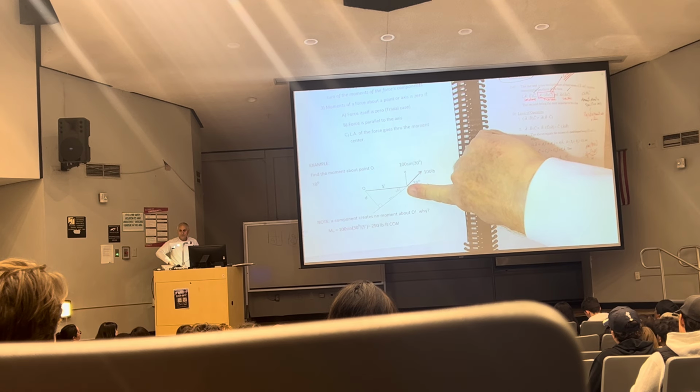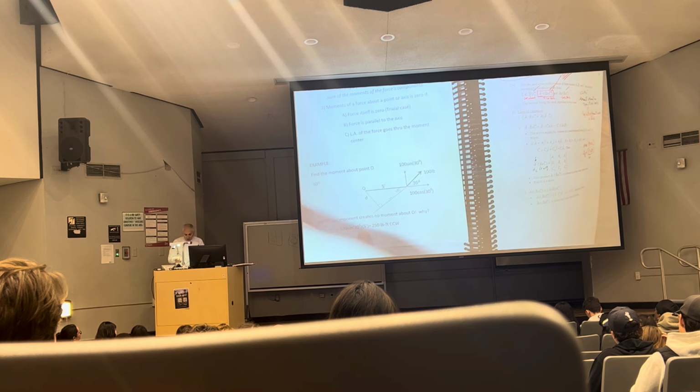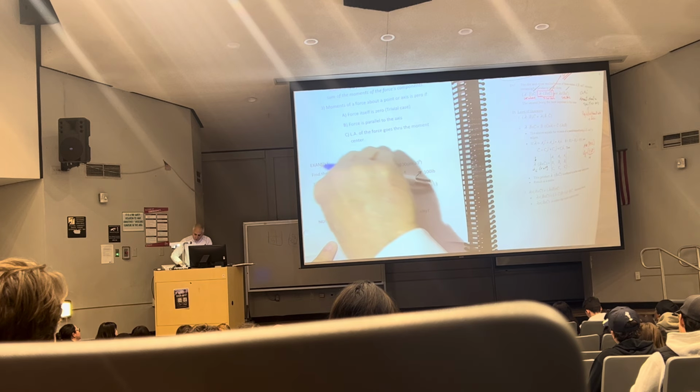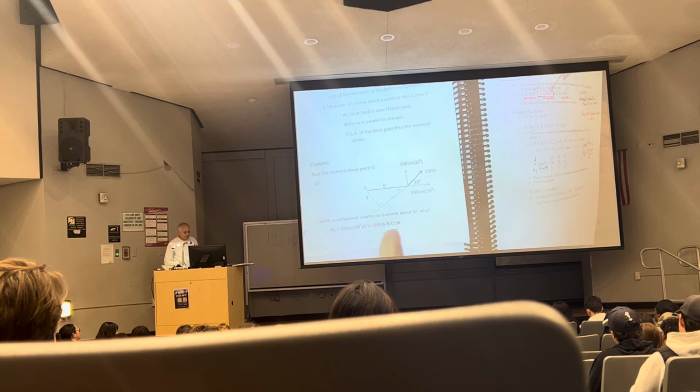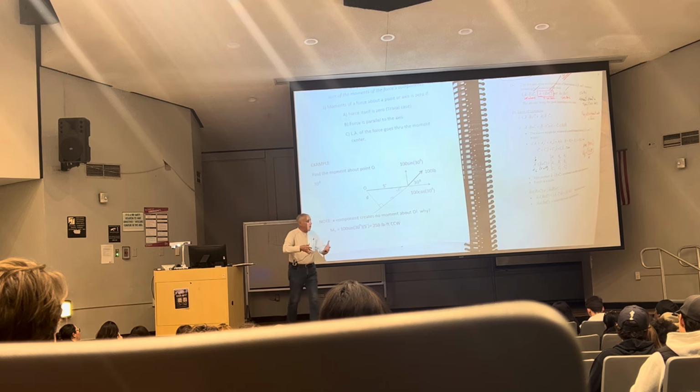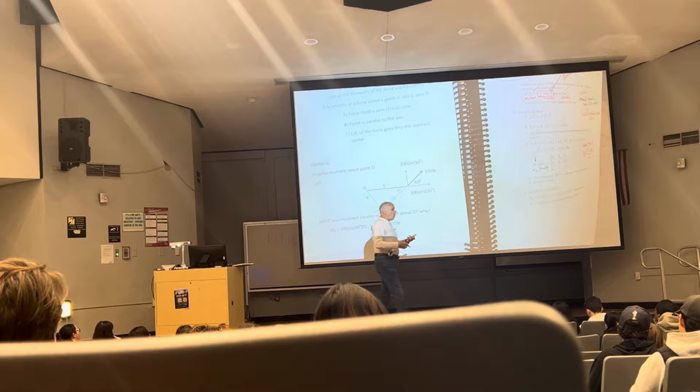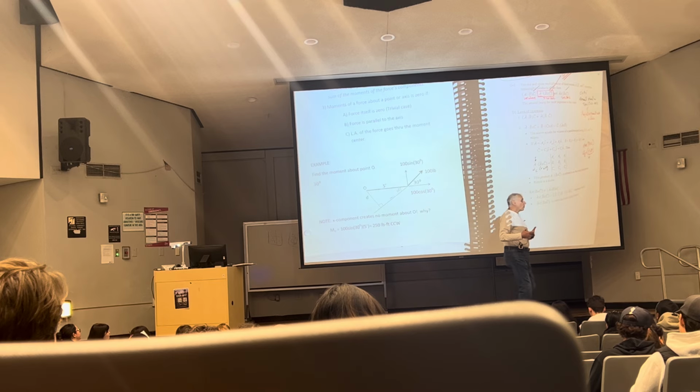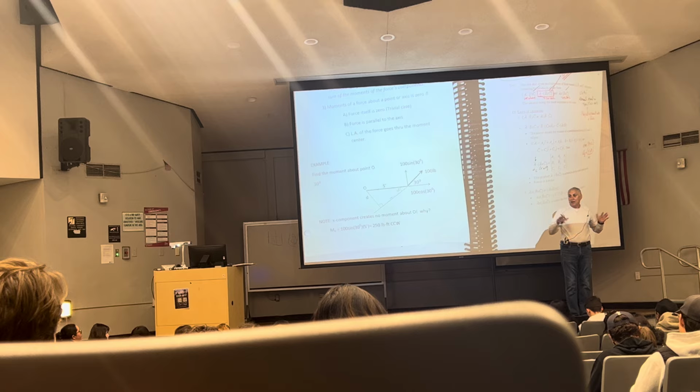That's it. So my moment is 100 sine 30 times 5. And if I move it to here by the principle of transmissibility and go around O, that is counterclockwise, as you see, CCW. Yes? So you just saw Varignon's theorem in action, and you saw, hey, when a force goes through the moment center, it creates no moment.